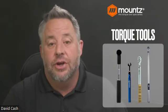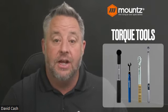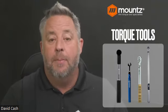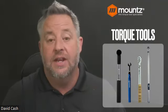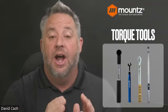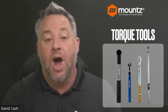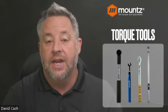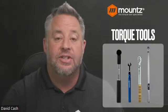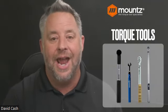The next style of wrench is going to be the most popular and most widely used wrench in the world, and that is going to be a click wrench. Now, for most click wrenches, the spring compression happens inside of the tool itself. And then there's a little block that is inside of there. And once there is a certain amount of pressure on the spring, that block will simply rock to the side. And that's where we get the click. So that's called a jump block or pivot block. And once that happens, the operator needs to release the wrench to not add additional over torque.